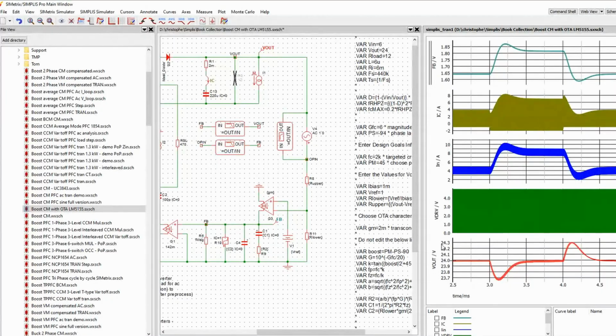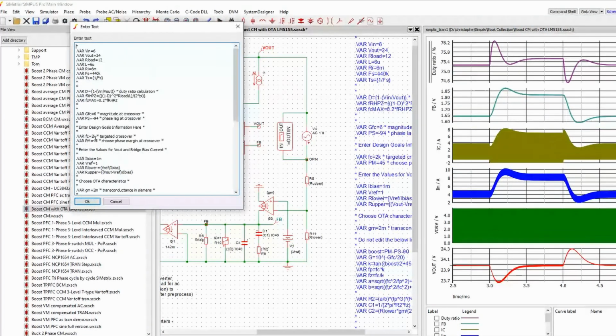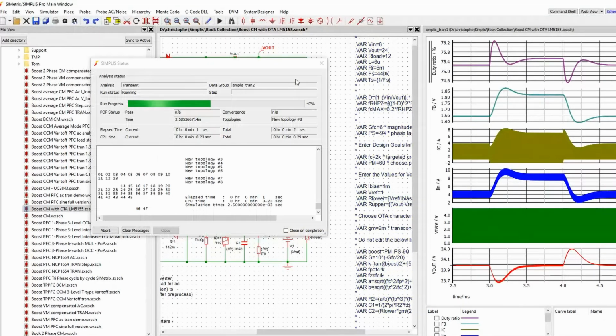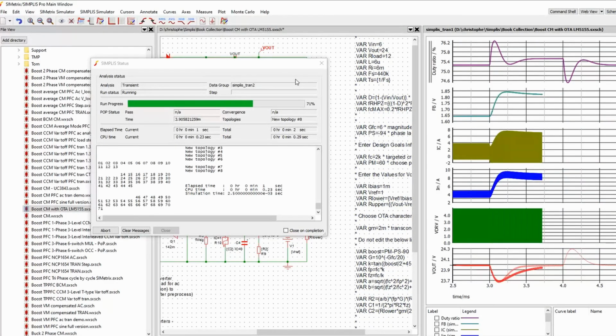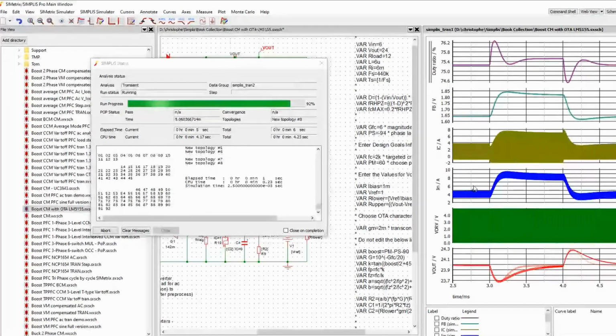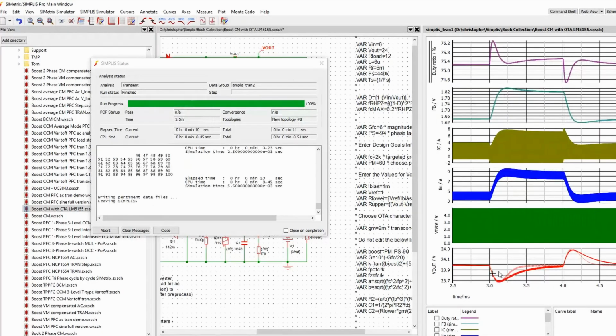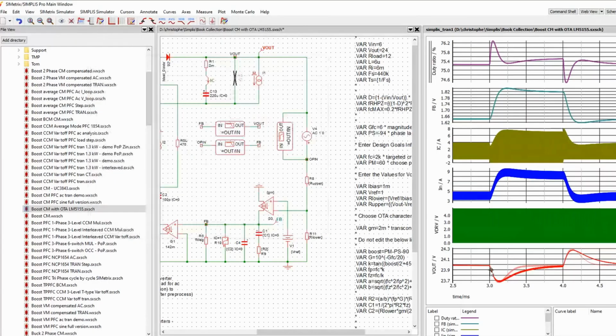the specific response. And now if I change the phase margin back again to 60 degrees, you see exactly what is expected. So here, the transient response, the drop that you can see here depends upon the ESR of the output capacitor, but also upon the capacitance and the crossover frequency, marginally above the phase margin. So I didn't change the crossover frequency, so the drop here is about the same.